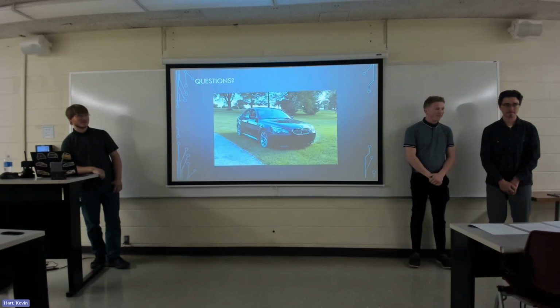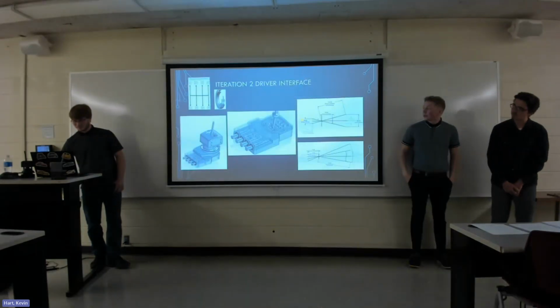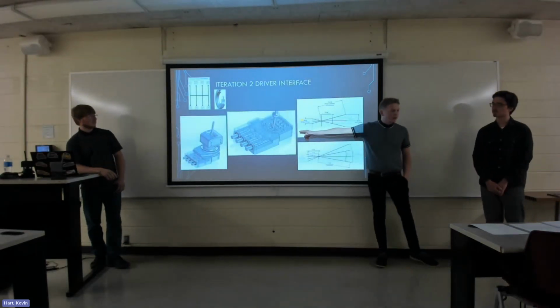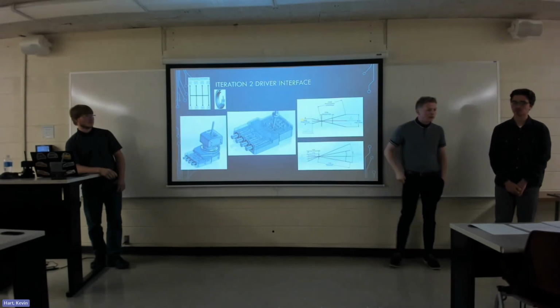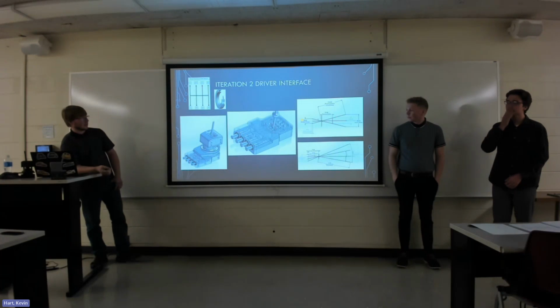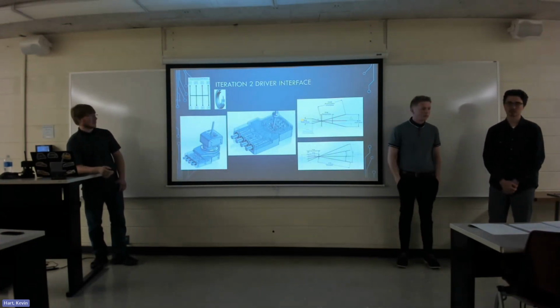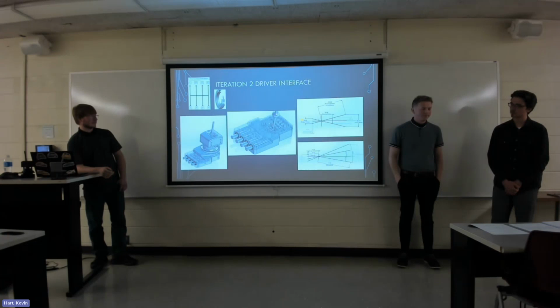I might have missed it when you said this, but a couple of slides back, you were talking about a fluid filled. Yeah, that whole lower assembly we're going to fill with fluid to reduce the friction within it. Some gear oil, probably a 75W-90. It may not even be necessary to do a gear oil, maybe even just a light grease, something along those lines. Yeah, because if it's oil, then you have to seal it really well. So primarily for ease of motion.